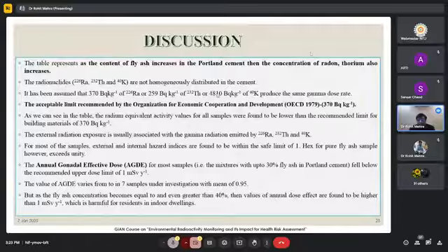So what I would suggest from our studies is that the government should think of other parameters, and how they could advise the cement companies to use fly ash up to a maximum level of 40. That is very important.